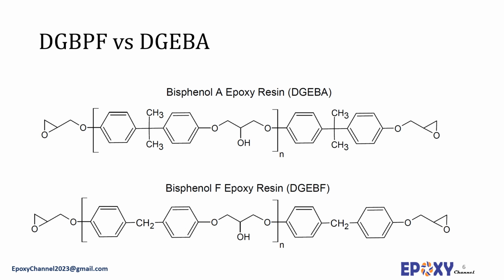The presence of bisphenol F in the structure of the diglycidyl ether bisphenol F resins does not adversely affect the mechanical properties of the cured thermosets. Therefore, the mechanical properties of diglycidyl ether bisphenol A and diglycidyl ether bisphenol F resins are comparable. Moreover, diglycidyl ether bisphenol F resins have a similar chemical reactivity compared to liquid bisphenol A epoxy resins.